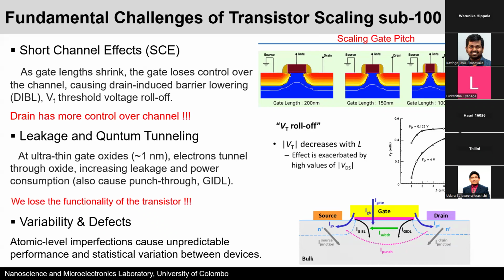And the drain, for the functionality, I told you, we also have to apply a particular voltage to the drain and also to the gate. So from the drain onwards, there are certain field lines that come and stop at this channel, right? These are like fringing fields that are coming from the drain into the channel, close to the oxide.